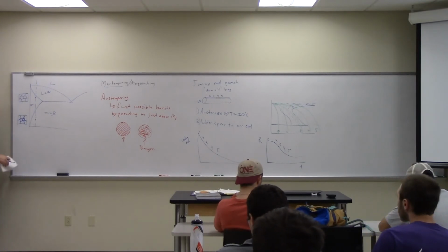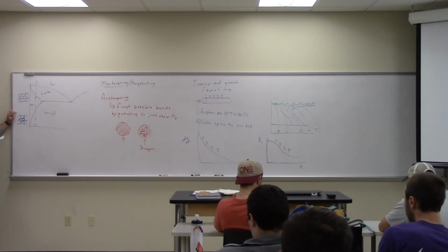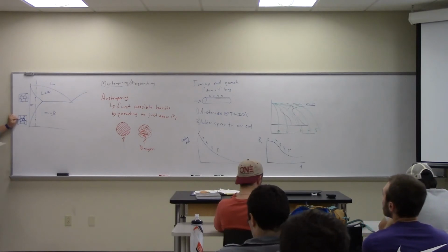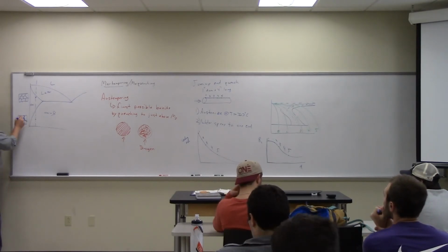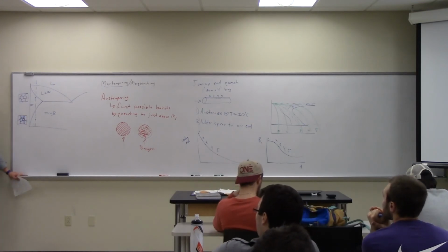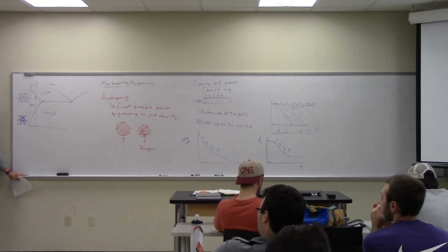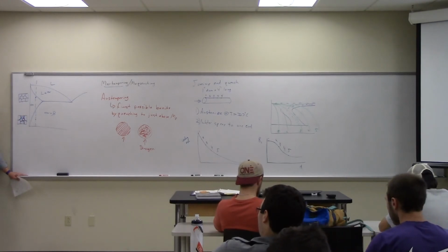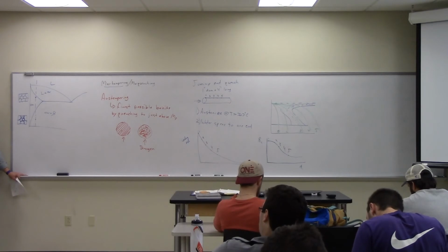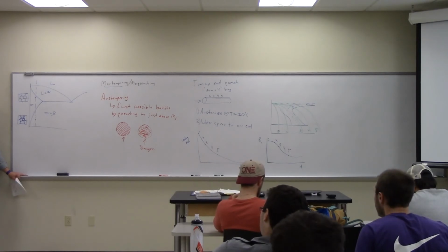So what I can do is, but the problem is, from a strength standpoint, this doesn't help me at all. Because now all my beta's at the grain boundary, I can still propagate dislocations across this alpha without anything stopping it, other than the normal strengthening mechanisms of interference with dislocations or dislocations running into impurities or whatever. But there's a lot of space for the dislocations to propagate. So this material is not stronger because the beta is not doing anything to stop the deformation, the propagation of dislocations.